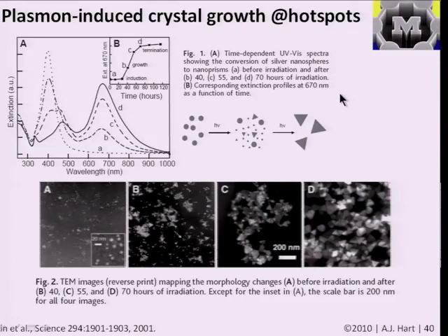Okay, so another example that I think is pretty interesting is how this principle can be used, for example, to process materials, and can also be used to characterize the production of materials. Because if you have, for example, a solution in which you're making some nanoparticles along the lines of the process of, say, nucleation and growth that we'll address later, and you're making structures that have these properties, you could use the principle of surface plasmon resonance, or this change in optical properties, to monitor your process.